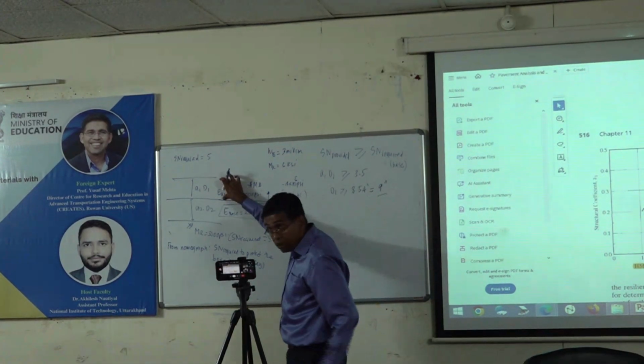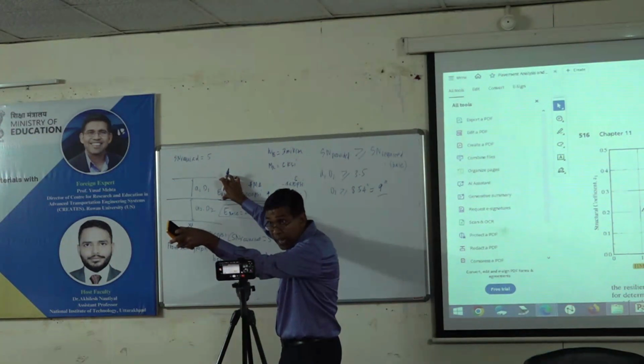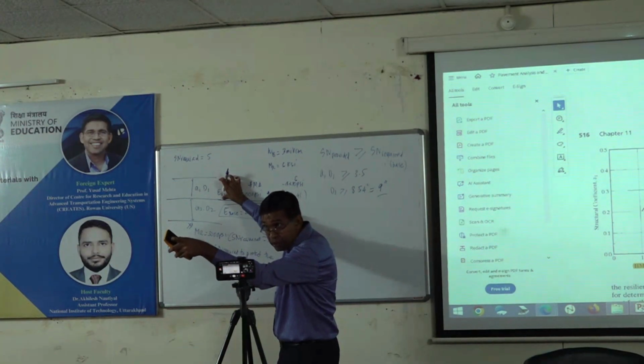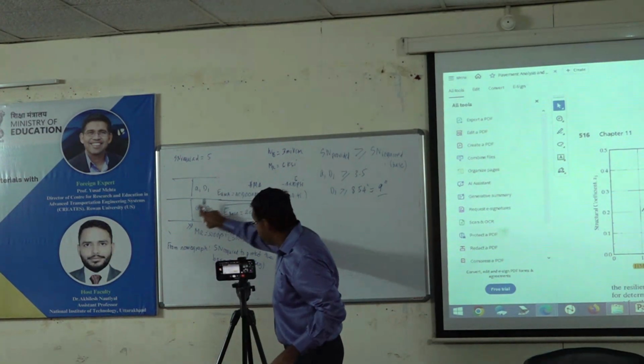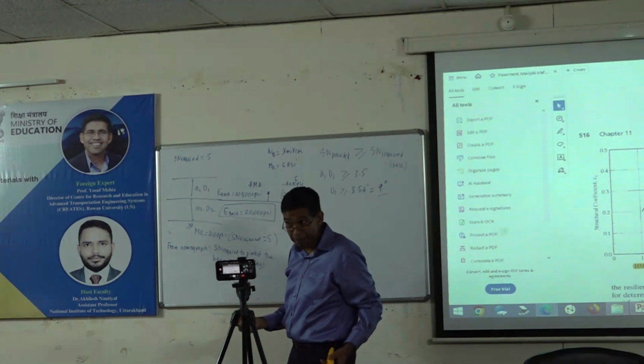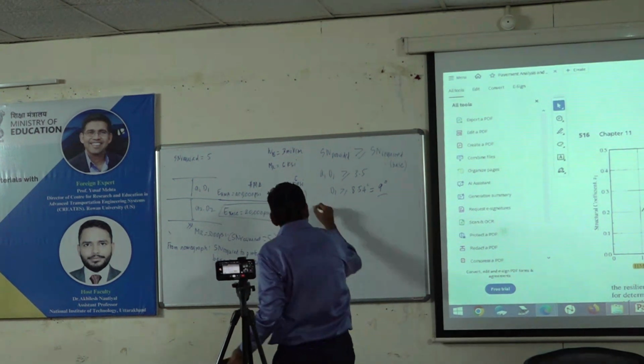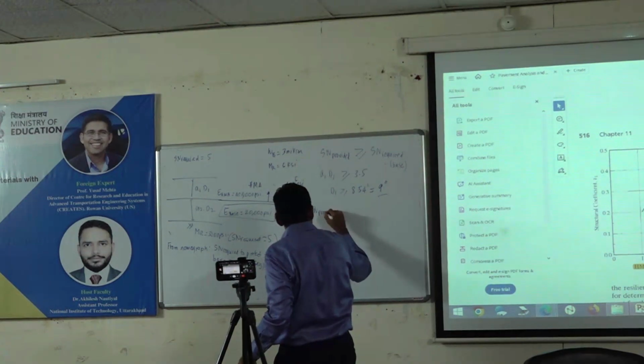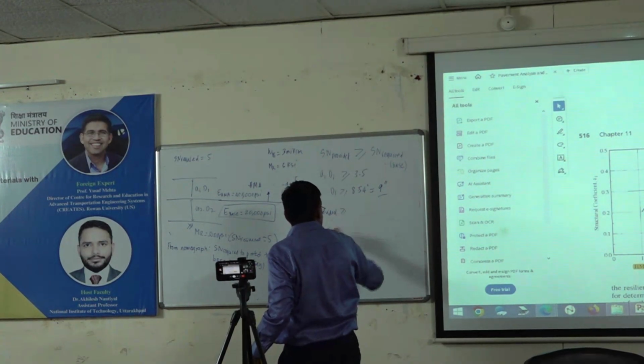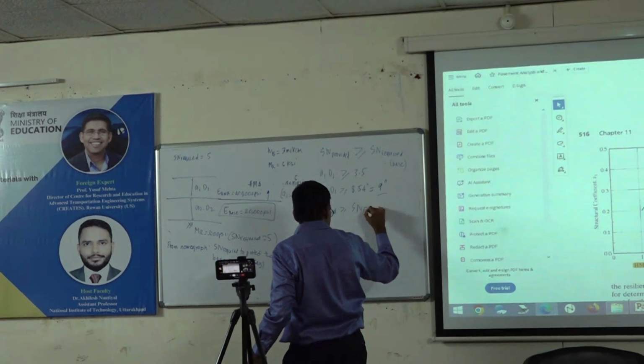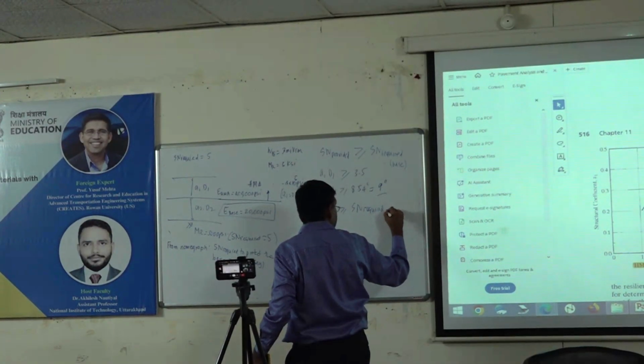Remember the number first. How much was it? 12.5 for the hot mix asphalt from the previous number. Now I have to find this D2, correct? Everybody with me, right? Now SN provided has to be greater than or equal to SN required to protect the subgrade.